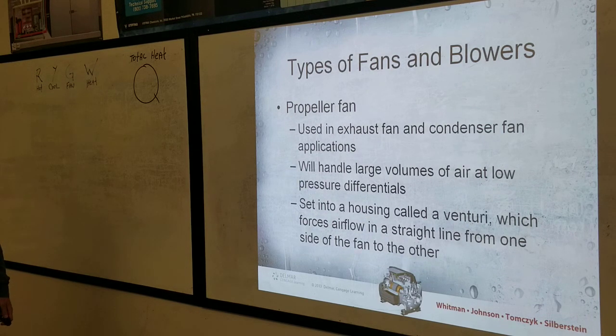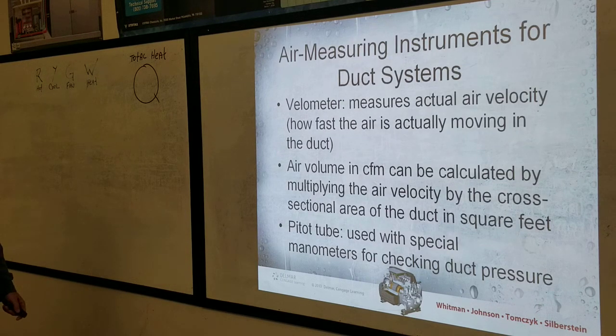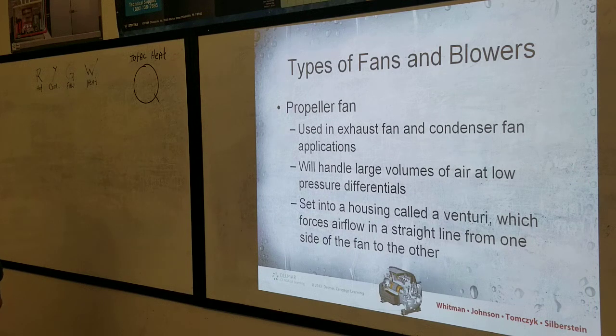Propeller fan. Used in exhaust fan and condenser fan applications. Will handle large volumes of air at low pressure differentials, set into a housing called a venturi, which forces airflow in a straight line from one side of the fan to the other.